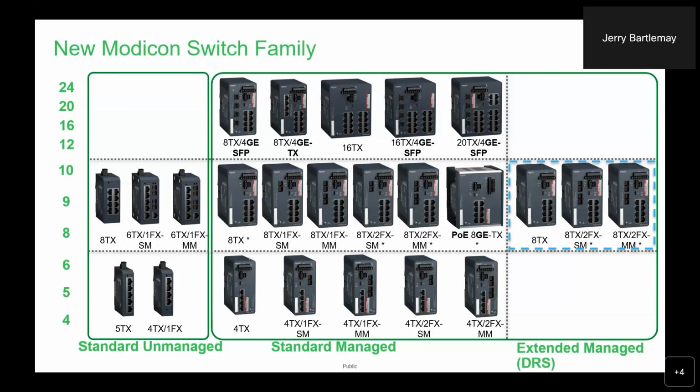And so we're fully compatible with those, but we do not offer the entire Hirschman line. We do the bulk of it, and it's actually, in my experience, pretty rare that we need something above and beyond what we can offer, unless it's a layer 3 switch. The dual ring switches are the exception to that. Those are custom configurations made for us specifically for the Ethernet remote I/O environment, and so there is not a Hirschman direct equivalent for those.